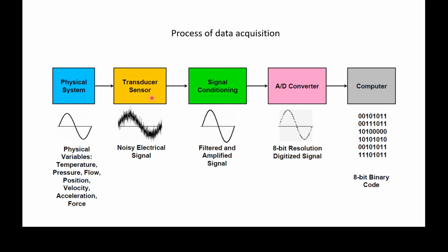One of the ones that we use commonly uses a special kind of electrical resistor, where when we put a current through a resistance, we tend to heat it up. And then when we blow air across that, we will cool it down according to the flow. And so if we have a measurement of what the resistance is for our given current through it, it will change as we cool it or warm it with the flow through the transducer.